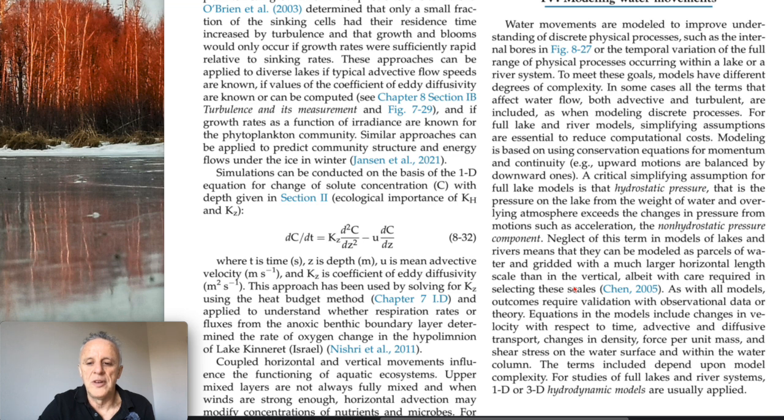Modeling is based on using conservation equations for momentum and continuity. For example, upward motions are balanced by downward ones. A critical simplifying assumption for full lake models is that hydrostatic pressure, that is the pressure on the lake from the weight of water and overlying atmosphere, exceeds the changes in pressure from motion such as acceleration, the non-hydrostatic pressure component.